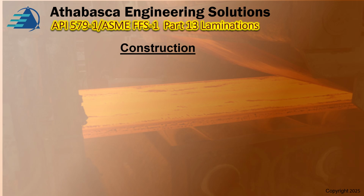So let's look at the material, the construction, what the pressure vessel designer had done with this vessel and how he constructed it. We have the materials of construction, which is SA-516 Grade 70 plate, a very commonly used structural plate for pressure vessels in the last 30 years in North America.